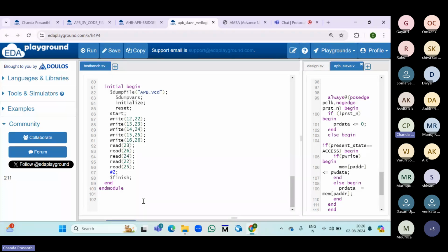If you directly go with the SystemVerilog test benches, there will be so many scenarios where you won't get the output. Even if there are no design errors and no test bench errors, you still won't get the output, and you will lose confidence about where the error is coming from. First try with the Verilog test bench. If it works properly, then you will be confident that the design is working and the output is correct. Then you can develop the SV test bench.